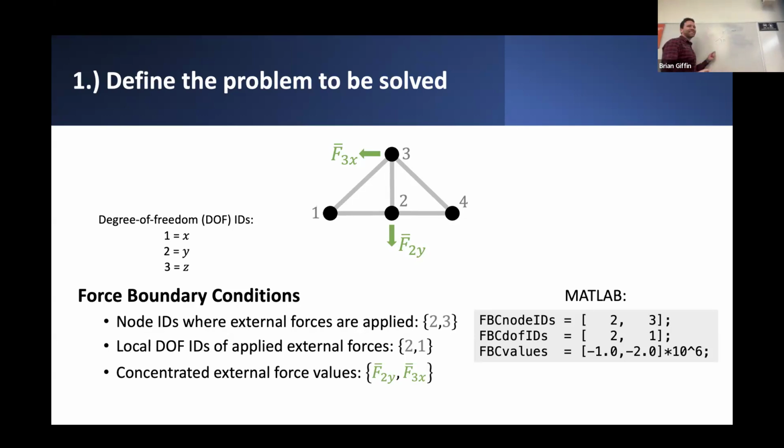You could represent that just in terms of its components. You'd have to break up that vector into, let's say, f cos theta and f sine theta, and then prescribe each of those independently as the x component of force and y component of force applied at a given node. So you could do node 2, node 2, node 3. Yeah, pretty much. If I have a force that has components in the x and y direction, you'd have to say node 2 has both an x and y component. So you'd have to double list node 2 and then list off its individual components, x and y.